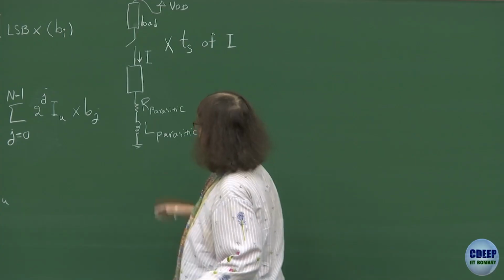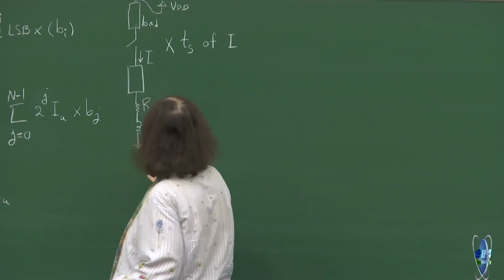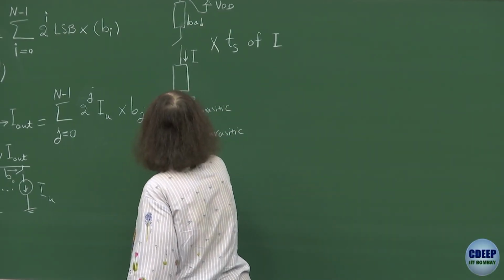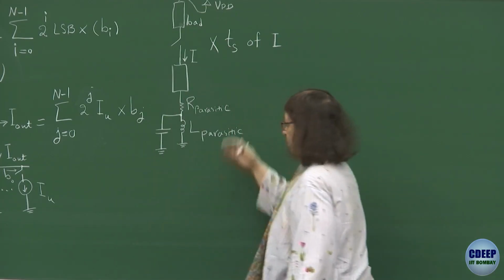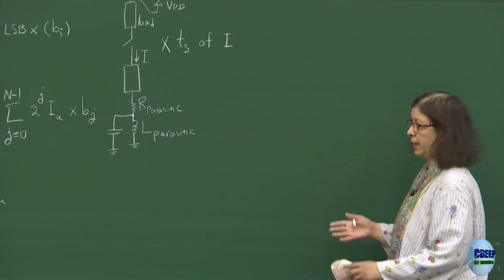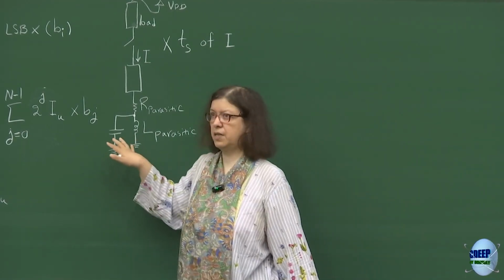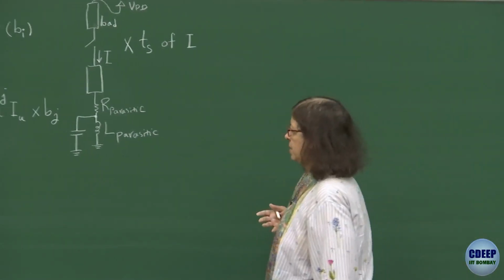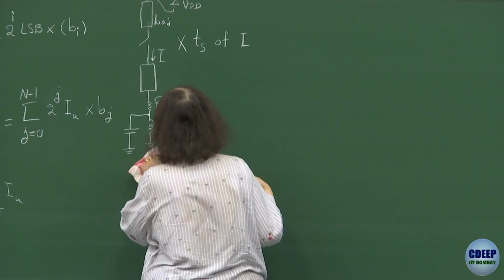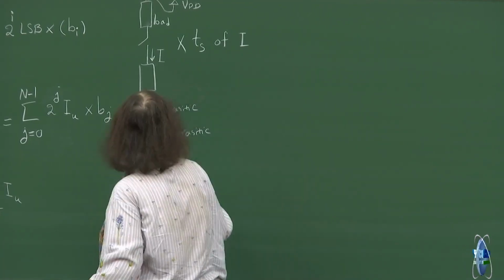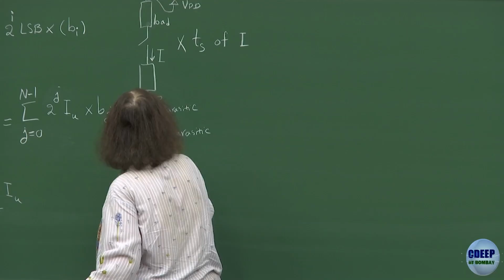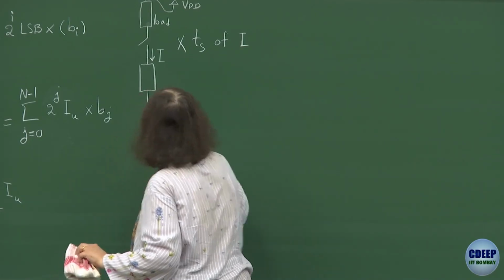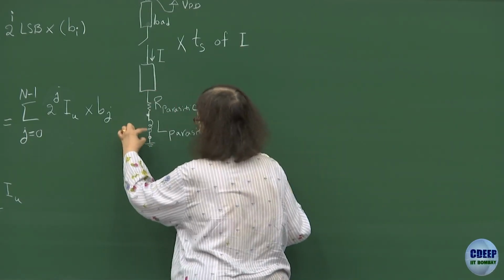Another problem is the equivalent inductance of these interconnects as well as the connection to the outside world. That's why usually there is a capacitor also here, which is called a decoupling capacitor, to reduce the effect of the inductor. And this we actually put on chip. It's a huge capacitor, but it's okay. You have empty space on the chip. So therefore, this is not actually the ground. So eventually, this node is outside. This node is inside the chip. And this inductor is sitting in between.